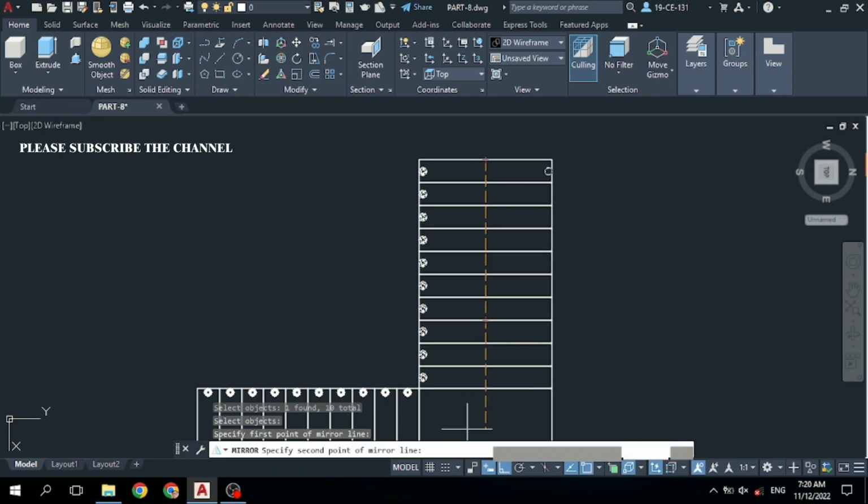Because ortho is on and this is a mirror line, click here and then click on no, I mean do not remove this part, so click on no. Now you can see it is mirrored to this side.